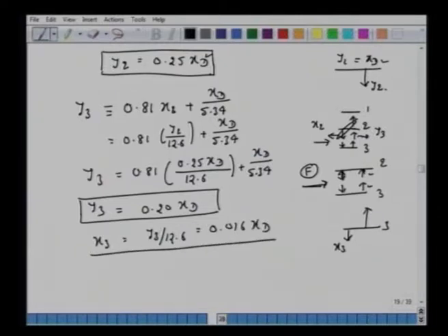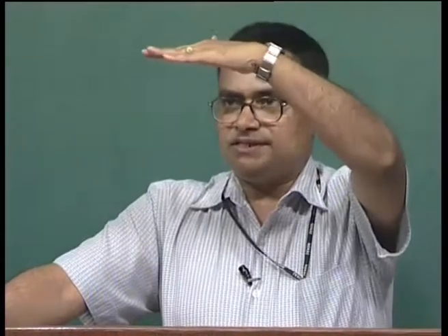So let's try to understand what we're doing here. Again, let's discuss it. We have this feed which enters between stage 2 and stage 3. Now this is a mixing zone, okay, and we made use of energy balance. If you recall, we had the total balance: F what enters, and two streams L and L bar, and we have G and G bar. Go back to your lecture notes. We wrote down this overall material balance, and then we wrote down this energy balance, or the enthalpy of all the 5 streams, 2 liquid and 2 vapor streams with the feed here. Okay, then we got this Q line.